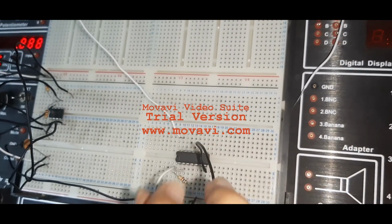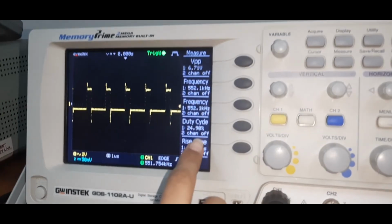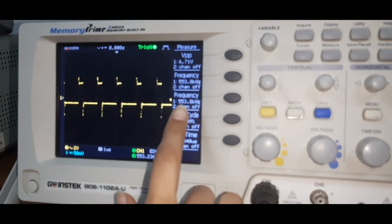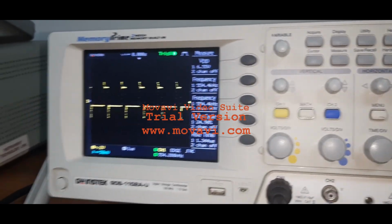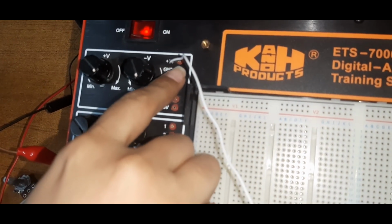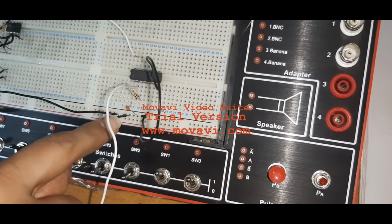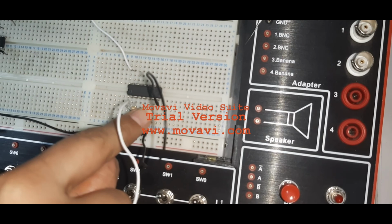When I connect this circuit and then see the output at pin number 2, there will be a square wave with a duty cycle of 25 and a frequency of 553 kilohertz. It is due to the DC power supply of plus 5 volt that is applied to this circuit. Now the frequency of oscillation depends upon this capacitor, and the duty cycle will depend upon this resistor.